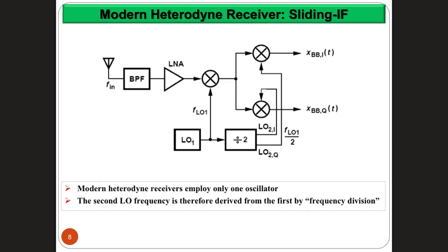If we look at the heterodyne receiver with zero IF second stage, and we want to use a single oscillator for that one, then we end up with mandated values for our local oscillators. So I want to create, for example, a local oscillator that brings the signal to some intermediate frequency and then derive another frequency from the same oscillator to bring the signal finally to the baseband.